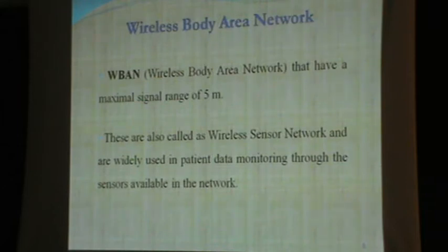And if you want to incorporate all these things, whatever sensor you are going to use has to be a smart sensor. Smart sensor in the sense that it should have the capability to condition the signal and to digitize the signal, and then you should have a transceiver for sending the information to the medical center. Or if there is any feedback given from the hospital to the patient, you need to be in a position to receive that. Therefore, you require a transceiver.